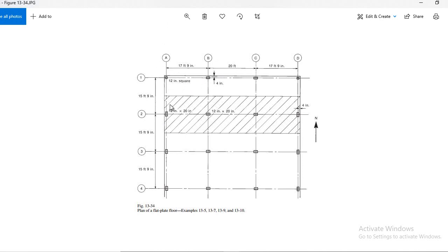Similarly you got the loading, the total load coming from this side beam, from this side beam, and from this one. Adding these three beam reactions over this column, you have moments Mux, Muy, as I explained in lecture number 7, I think. Please go there and watch that lecture. After that you will be able to design this column and this column. Clear?